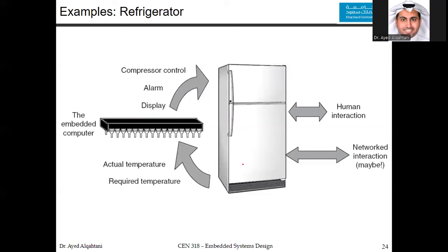Here are some of the things that you need to be knowledgeable about, like the microcontroller performance. You have the processing power. We will give some indication of the processing power by knowing how many bits you are dealing with. So you have 4 bits. This is in the data bus. Remember the PIC 12? We said that the bus has 8 bits. So the PIC 12 is of this processing power. So you have 4-bit microcontrollers, 8-bit microcontrollers, 16-bit microcontrollers, and 32-bit microcontrollers. For the microcontroller that we are going to study, PIC24, its type is actually 16-bit microcontroller.